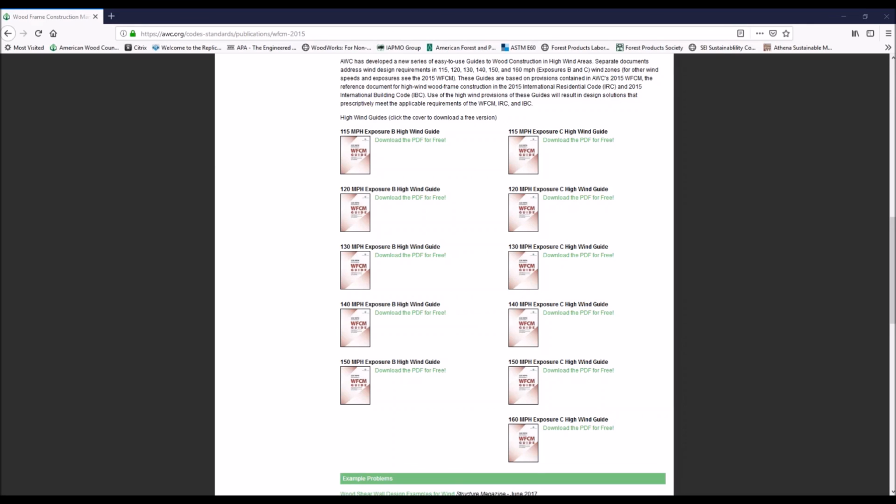And did you mention what method? Yeah, in version 12, it would be the Diekmann method that we're using for the force transfer around openings. As well, we have aligned our calculations with the APA calculator on the APA website, so users can have confidence that the software is doing the calculations as APA has outlined.